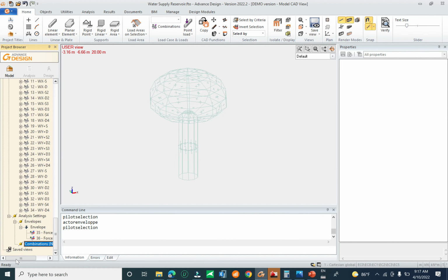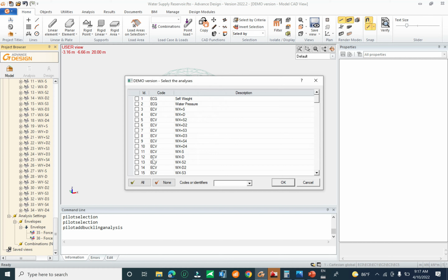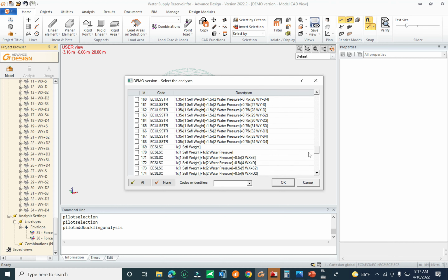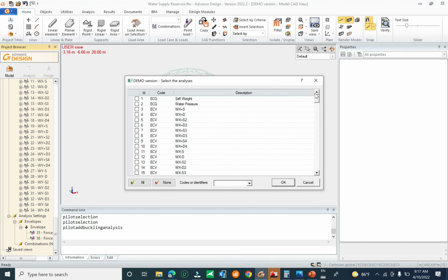And you can create for nodal analysis for the dynamic, or you can generate for the linearized buckling, nonlinear analysis, pushover for the dynamic analysis, or for the seismic analysis. You can check the option. Now I want to click on the linearized buckling. I want to analyze for the buckling, and you can select the load case relevant to your design project or the critical load case.